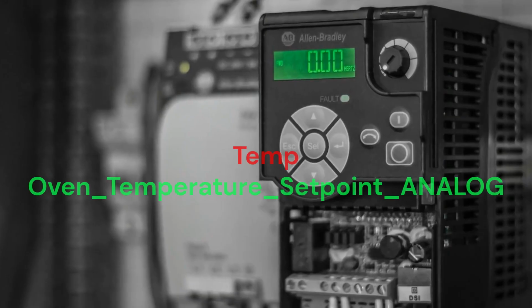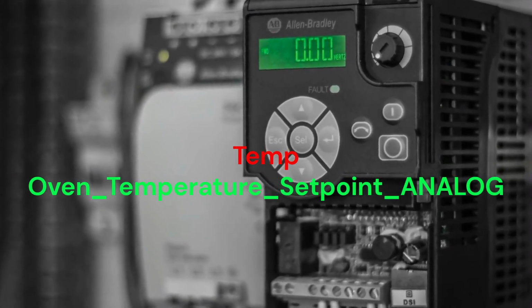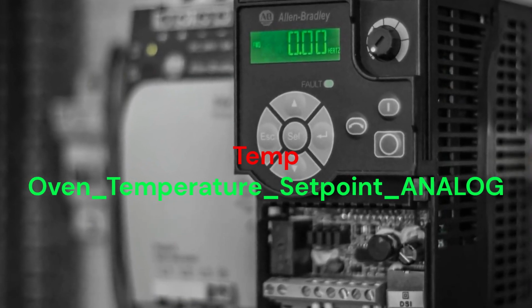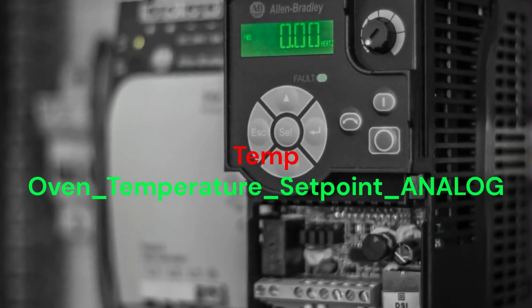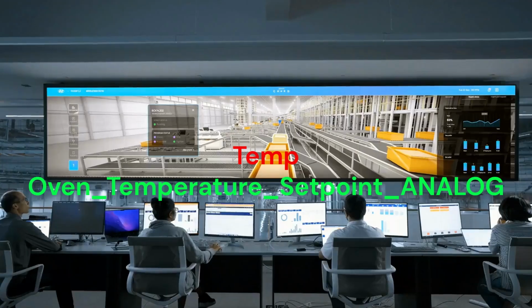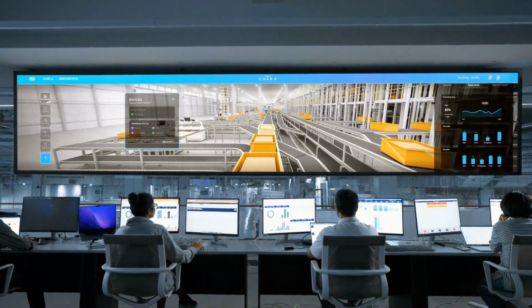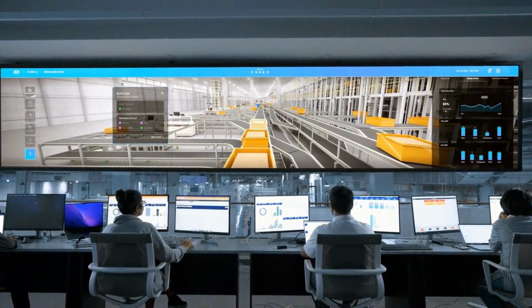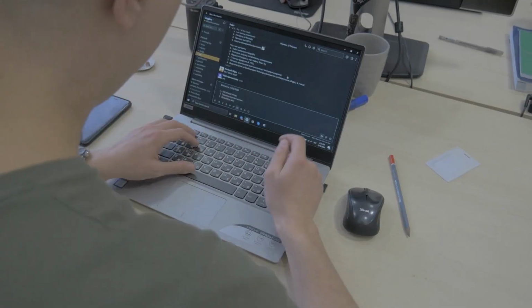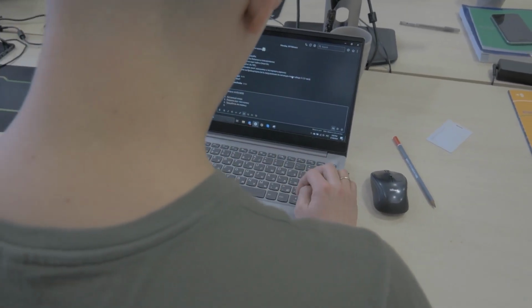Bad: Temp. Good: Oven Temperature Set Point Analog. The good name distinguishes between the actual temperature and the desired set point and indicates it's an analog value. Creating a solid naming convention for your PLC projects is a crucial investment that pays dividends in the long run. It's a simple change that can lead to more organized, readable, and professional code.